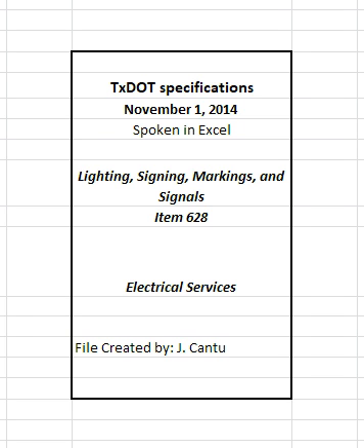Disconnect conductors and remove them from the conduit. Cut off all protruding conduit 6 inches below finished grade. Abandoned conduit need not be removed unless shown on the plans. Reconnect conductors and conduit to be reused when shown on the plans. Make all splices in ground boxes unless otherwise shown on the plans. Accept ownership of unsalvageable materials, and dispose of them in accordance with federal, state, and local regulations.